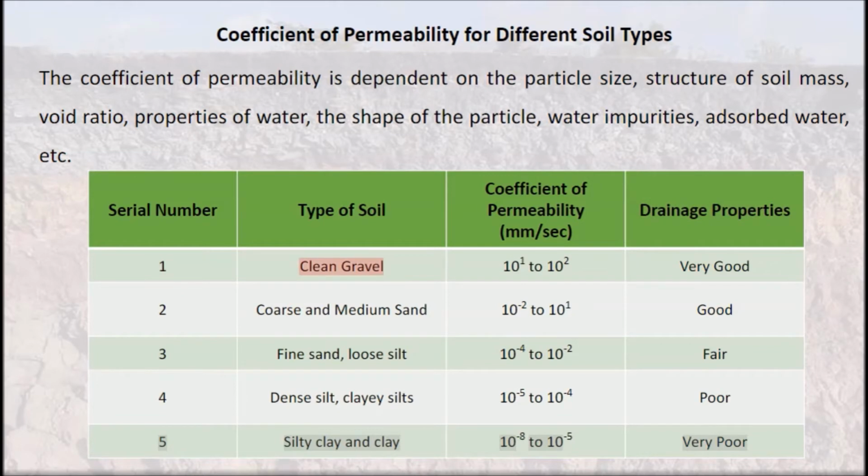Clean gravel, 10^1 to 10^2, very good. 2. Coarse and medium sand, 10^-2 to 10^1, good. 3.